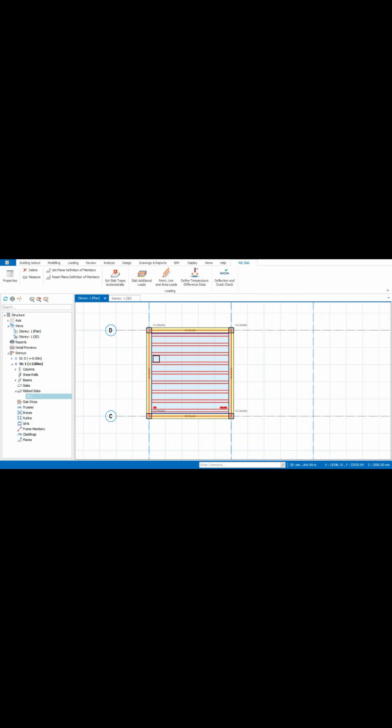Whereas you could also choose to draw a single slab strip on the area you find to be most critical, which we consider the rib around that region, and then use the rib around that region as a standard to calculate other ribs.